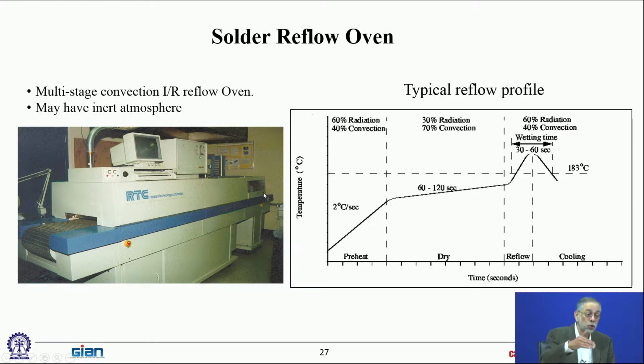And there again, you want to make sure that you're not in the pasty range, that the solder is completely solidified, otherwise the cooling air jets will move and misalign your components. Okay? So that's why it's so important to have a very narrow pasty range. And then the actual reflow zone is also bathed in gaseous nitrogen, an inert environment, otherwise there's excessive risk of oxidation at that time. Okay? Not all ovens have an inert atmosphere, but some applications require that.